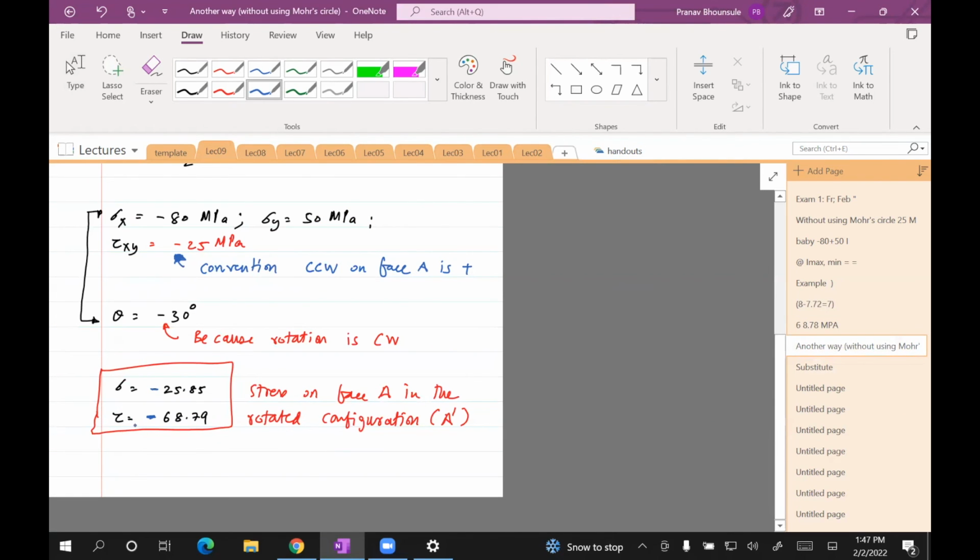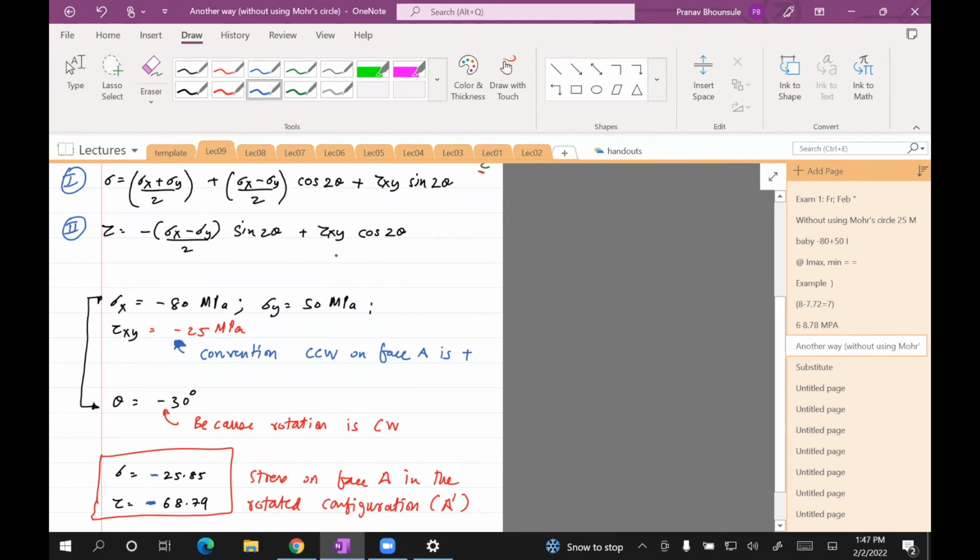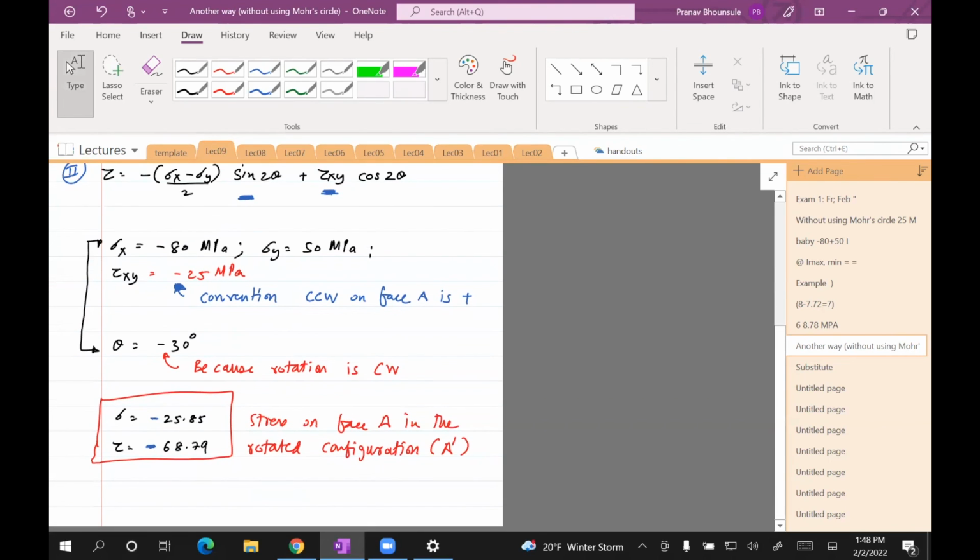And this should be the case because the convention is that whatever you got for the Mohr circle is going to be reversed for the plane stress element, right? So this is actually the right answer, and you should check this. In my notes, I'd done this calculation and I skipped over that it shouldn't be the same. You can put these values in and check. It should be negative, not positive.